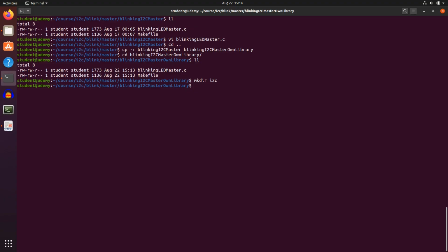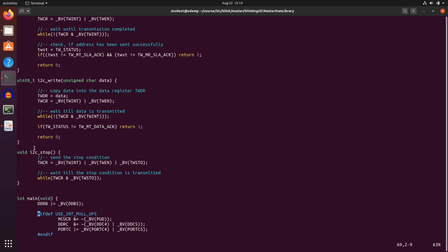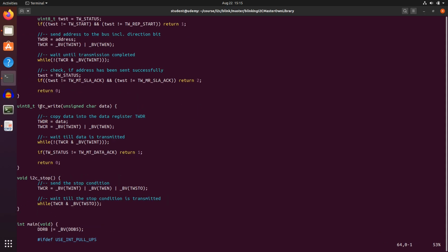The next step would be to create several files which contain different functionalities. What I mean by this is, usually, if a developer uses I2C start, also I2C init has been used, and most likely also I2C stop has been used. Therefore, these three functions I include into one file. The developer might not have used I2C write, but for instance I2C read to read from slaves.